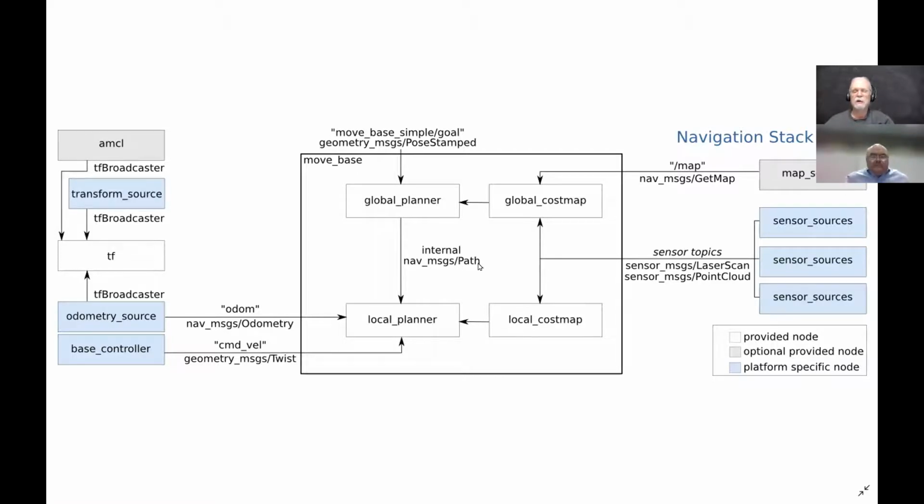You notice on here, he also left out the recovery behaviors. And I think from my point of view, if I'm going to do an Ackerman vehicle outside of my front yard, I would probably turn the recovery behaviors off, because they work best with a differential drive, and I don't want it doing stupid things to me.